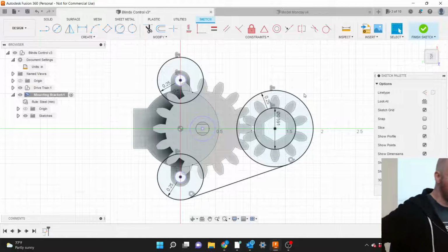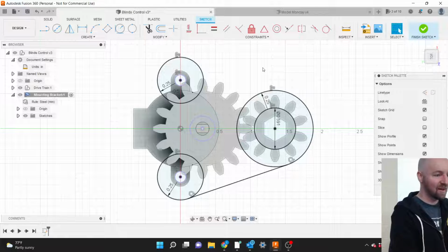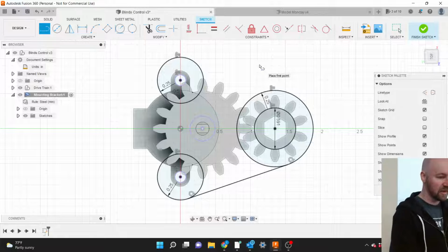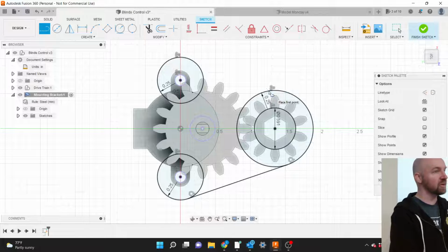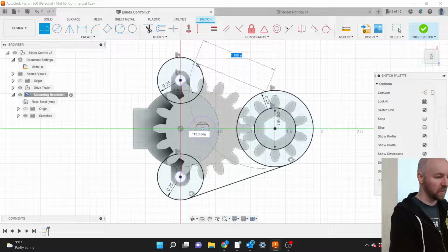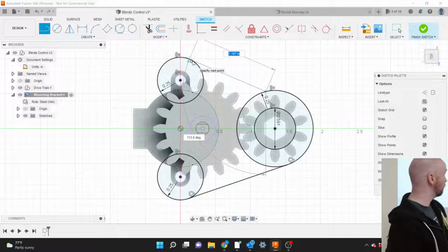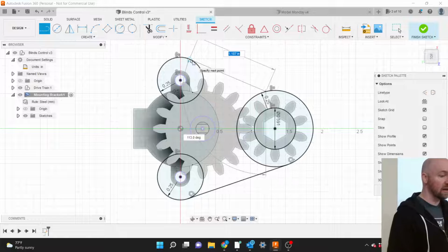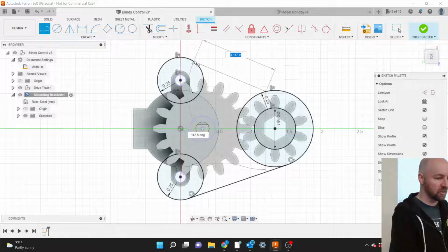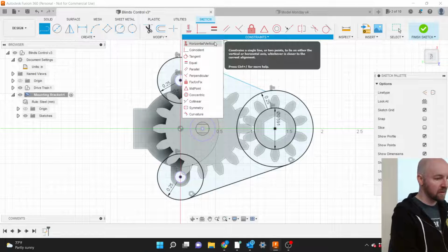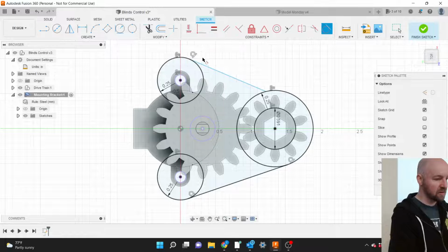Another way to do this would be to draw it right from the start, draw it right the first time. So if I grab my line tool again, it's easy to make your line tangent to the second circle, kind of just by chance. If I just hover my mouse over what appears to be tangent, then I get one of those tangents for free. The first point, I just clicked on the circle. And the second one, I can hover over it and get close, and then I get that tangency for free. And then I have to add, after the fact, that tangent constraint.